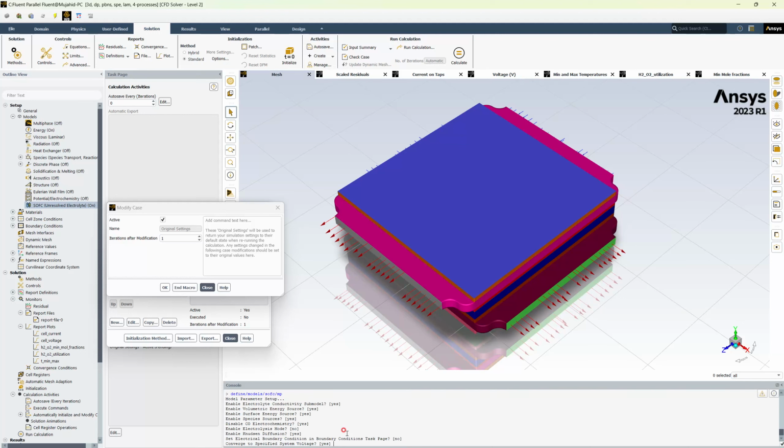specified system voltage, no, and total system ampere current 0.01. Enter. There is no leakage density, and the current under relaxation factor is 0.3. Okay, enter. The rest of the things are all the same, and we said we'll do end macro. Now macro initial is defined.